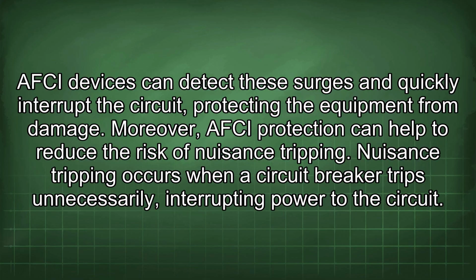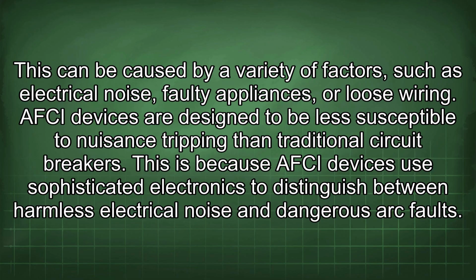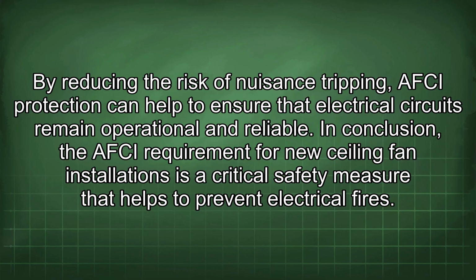Moreover, AFCI protection can help to reduce the risk of nuisance tripping. Nuisance tripping occurs when a circuit breaker trips unnecessarily, interrupting power to the circuit. This can be caused by a variety of factors, such as electrical noise, faulty appliances, or loose wiring. AFCI devices are designed to be less susceptible to nuisance tripping than traditional circuit breakers. This is because AFCI devices use sophisticated electronics to distinguish between harmless electrical noise and dangerous arc faults. By reducing the risk of nuisance tripping, AFCI protection can help to ensure that electrical circuits remain operational and reliable.